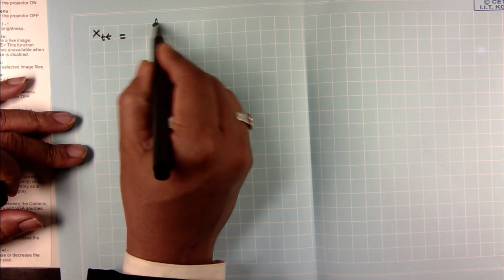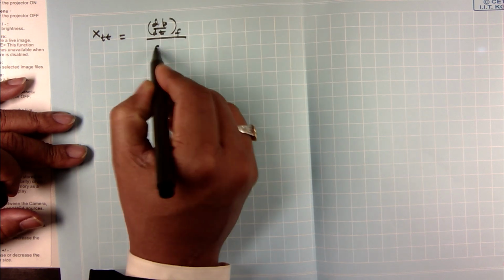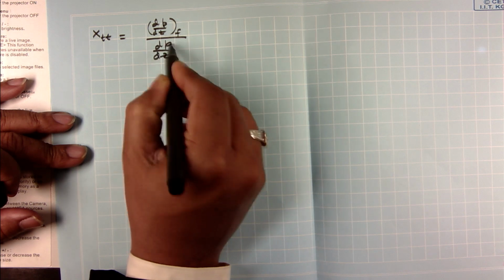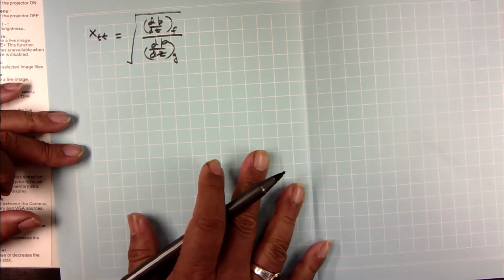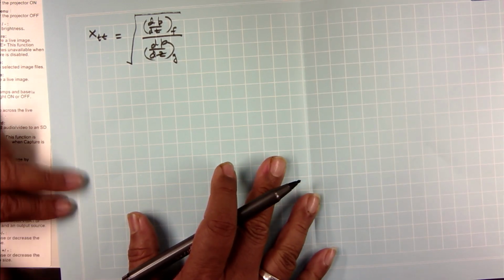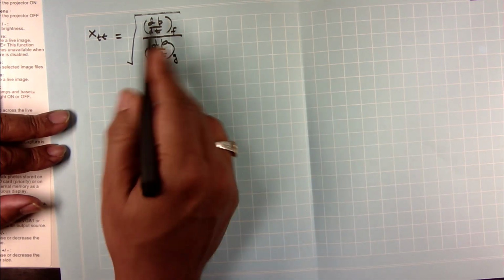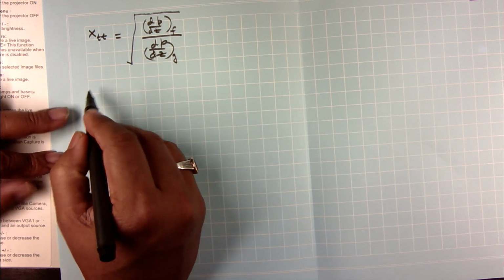Remember, we talked about Martinelli parameter, right? So what did we say was the definition of Martinelli parameter? You have dp dz for fluid divided by dp dz for gas, and I'm sorry I made a mistake, it should be the square root of this. Okay, that's the definition of Martinelli parameter. So similar to Martinelli parameter, this is for total pressure drop, right? Now if I only care about the frictional pressure drop,